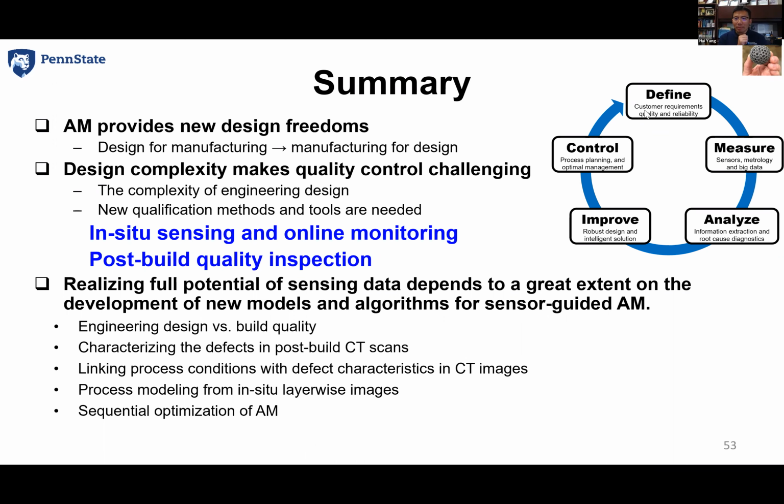If you look at the thin wall build, they have different kinds of support, because their width is different, so the support will be different. If it's too thin, it's very hard to support at the top level, for higher thin walls, so you will see the quality will be different. That's one support structure for thin walls. Recently, we are also looking at supporting structures for different geometries, using layer-wise imaging and the melt pool, to see how different support structures impact the quality and the geometry variations in the final build.